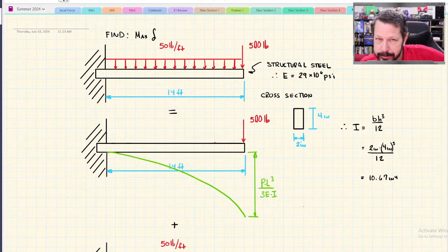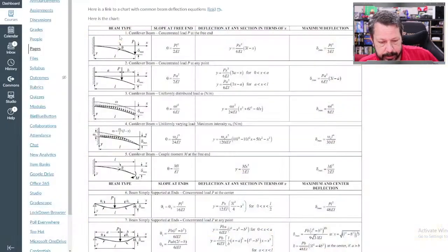Last time, just for the sake of developing the equations, we did measure x equals 0 at the free end of our beam. That was really only for figuring out those theoretical equations. Most of the time x is going to be 0 at the wall. You do have to check that with your picture.